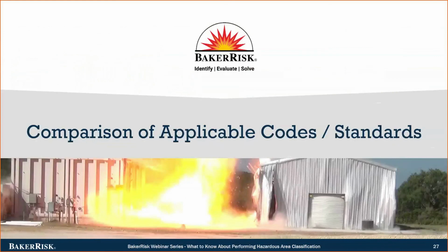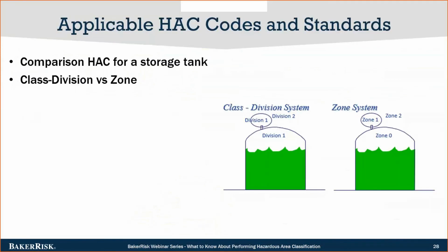Let's now transition and look at the applicable codes and standards. And what I'd like to do is focus on the two basic methodologies. And to do this, I'd like to look at a comparison of the hazardous area classification for a storage tank. The two general methodologies are called a class division scheme versus a zone scheme.